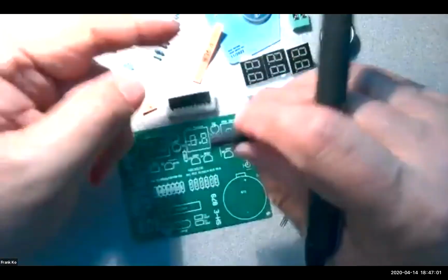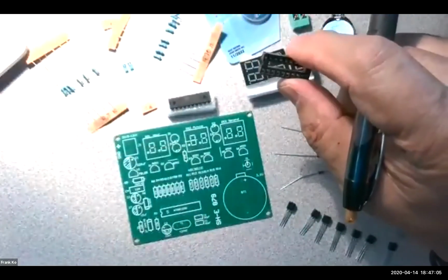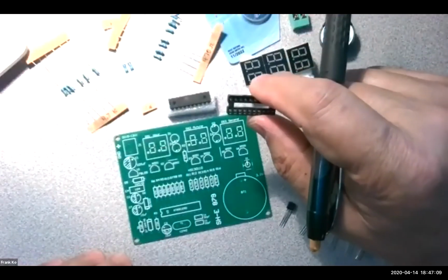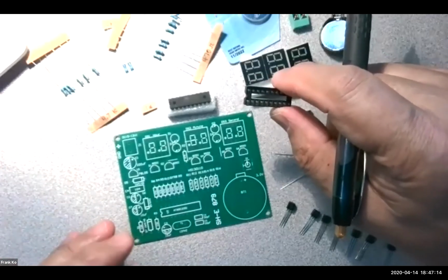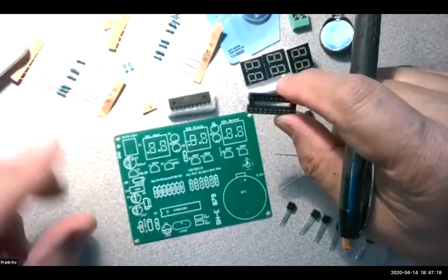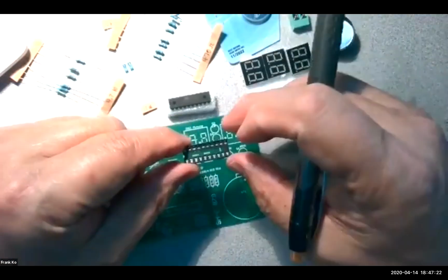When you sit down before you handle this, you should discharge any static electricity on your body onto any grounded part of your electrical system. Generally, if you touch the metal part at the back of your computer system, it is grounded, so that will take off any static charges on your clothing or on your body.